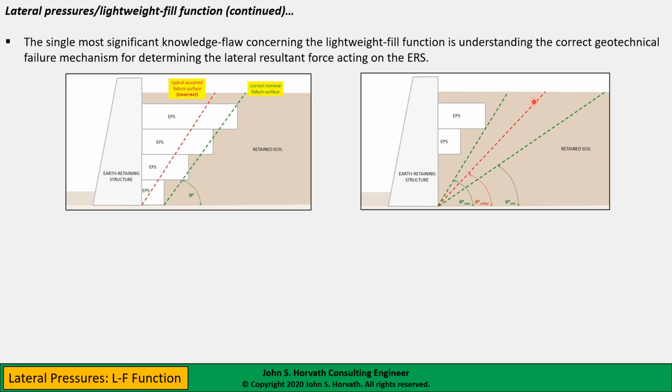The easiest way I've found to solve this is very simple to solve nowadays. I happen to use an Excel spreadsheet, the solver function, very efficient. If you look in older textbooks, it's what's called the trial wedge method. It used to be done manually. It's easy enough now to do by spreadsheet, and you simply find on a case-specific basis the critical failure angle. So in this case, this is significantly, in terms of mechanism, completely different than the full depth placement, the partial depth placement.